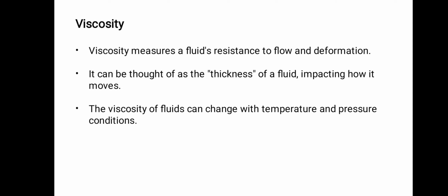Viscosity. Viscosity measures the fluid's resistance to flow and deformation. When we take honey and water, the water is less viscous compared to honey because the water has less resistance to flow. But honey or ketchup is very difficult to flow, it has a good resistance to flow. Honey is highly viscous, which represents the thickness of a fluid impacting how it moves. We can categorize viscosity into dynamic viscosity and kinematic viscosity. The viscosity of the fluid can change with the temperature and the pressure condition.